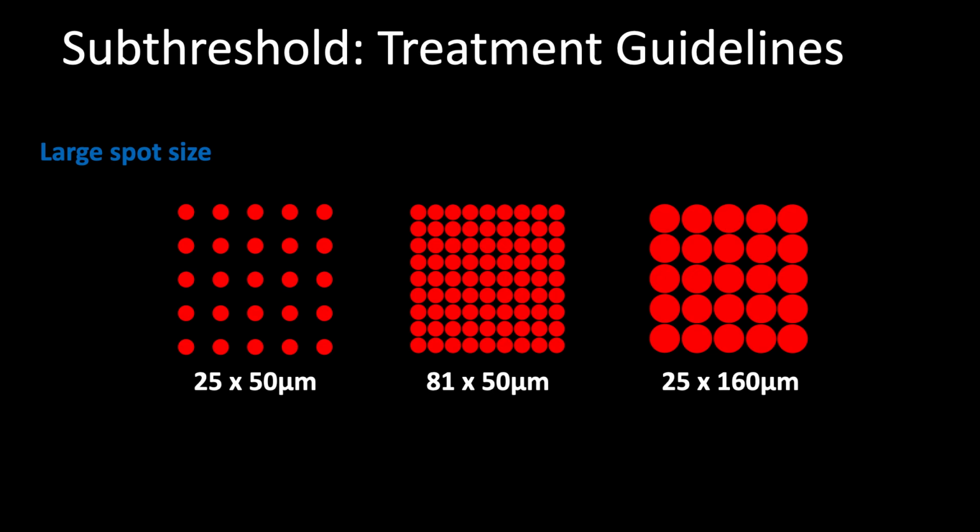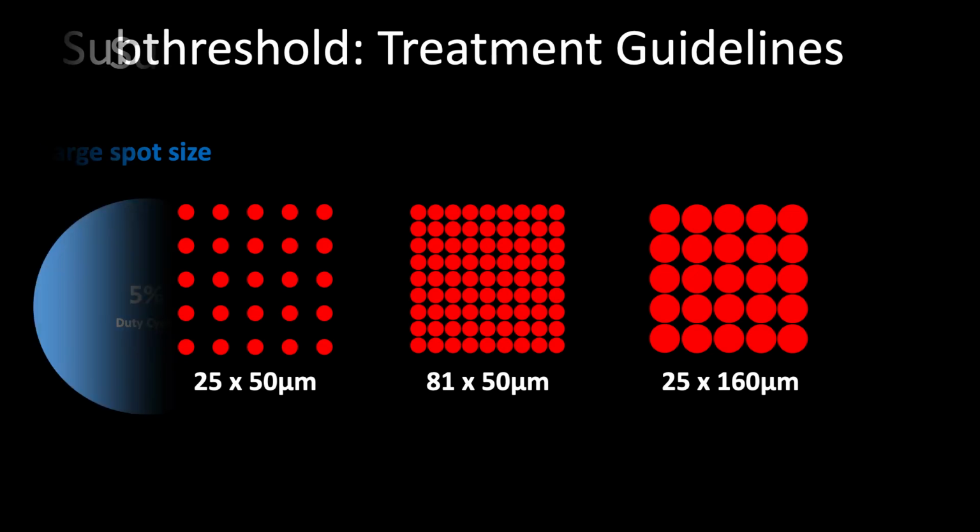But the problem is, you will recall that for each laser burn, the irradiance is determined by the radius of the spot size squared. So we would need a lot of power to do those higher spots to deliver the same energy. And unfortunately, the laser capabilities are not that high with the current technology.